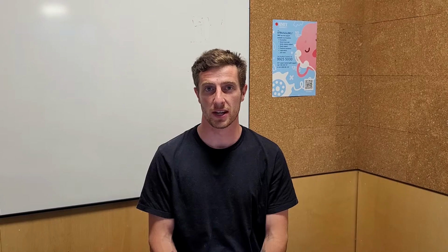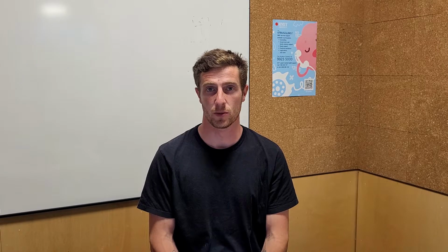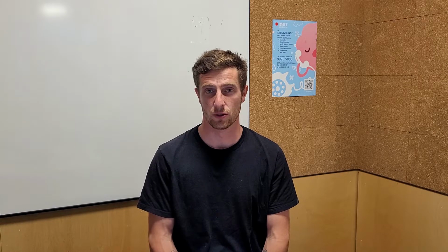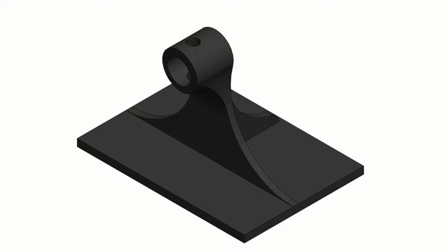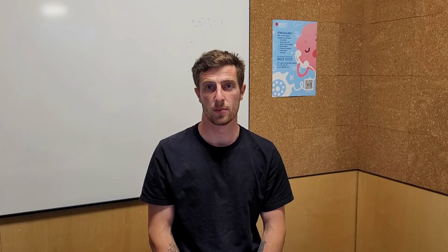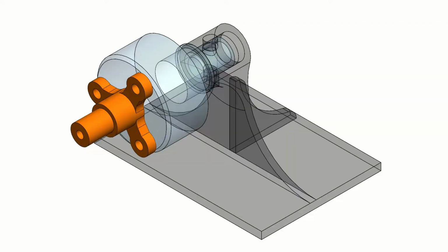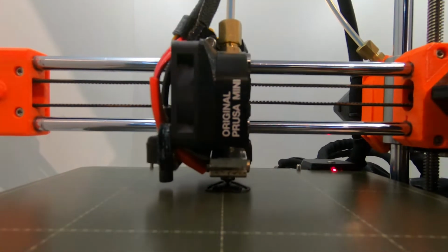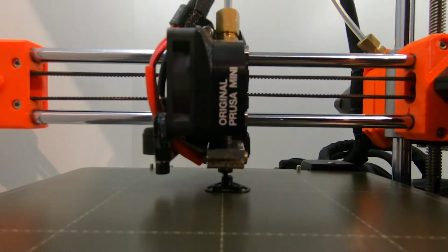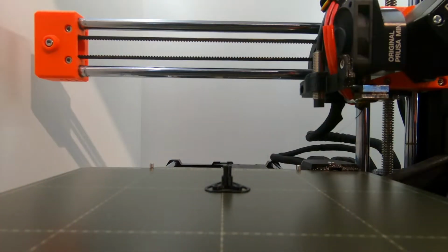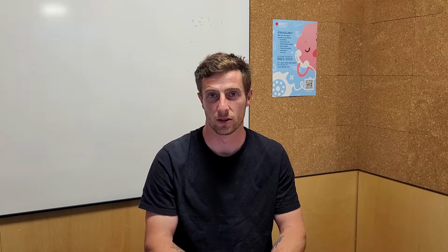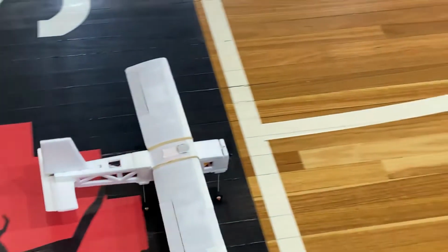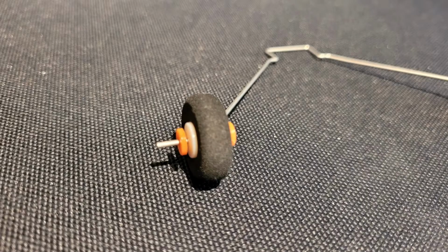The motor mount also had to be re-glued a few times due to its poor design. It lacked a flat surface to glue to, so a new one with a flat surface was designed and 3D printed. One part that broke almost every crash was the propeller shaft. It connected the motor to the propeller. It tended to shear off when the plane crashed near the ground nose first. This was also another component that was 3D printed. The landing gear was converted to a quadricycle configuration to aid ground stability and improve durability. After removing the cowlings to save weight, we had to make some collars to hold the wheels on.